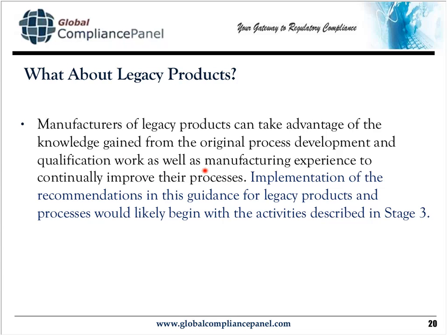And so what you do is use your manufacturing experience, look back over previous lots and see what kind of data you can get out of it, especially in terms of variation. If you look at your past lots, you should be able to get a good idea of where you're seeing a lot of glitches and variations in your process. And based on that, you can introduce numbers into statistical calculations.